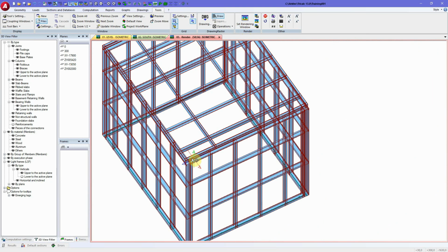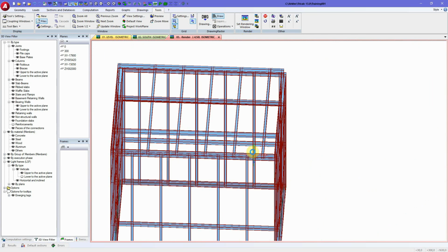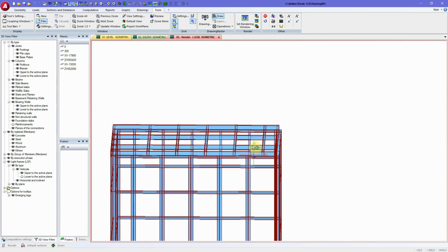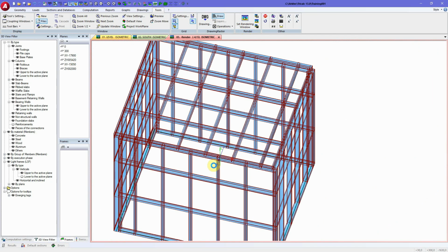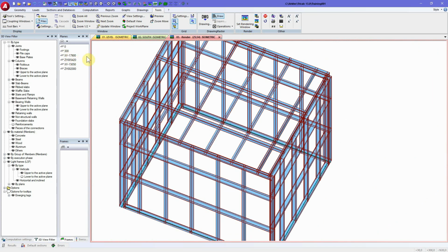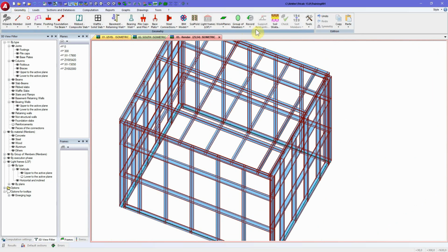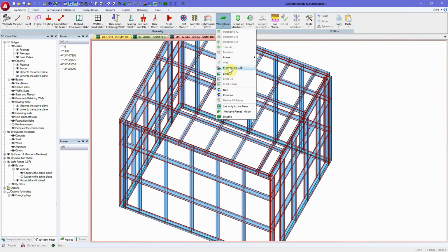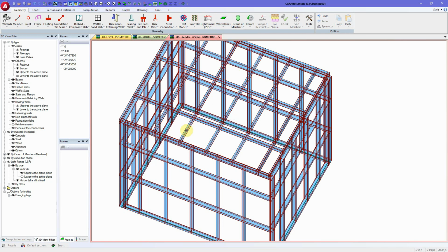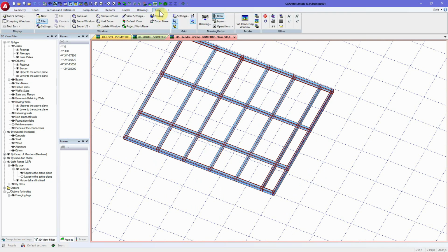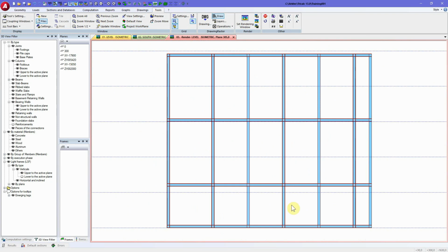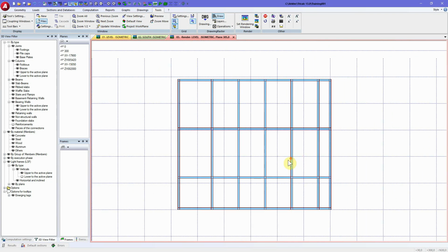For the reference of the elements, again, the rules are the same. So you can change the positioning of the slab elements according to the grid line that you have defined. If you want to change the plane of that grid, you just need to go to geometry, work plane, and select the plane for a work plane from the frame LSF. Just select the frame that you'd like to use to view at any time. And now let's say I'm going to project this work plane in my view here. Now you can see you can align your profile differently.